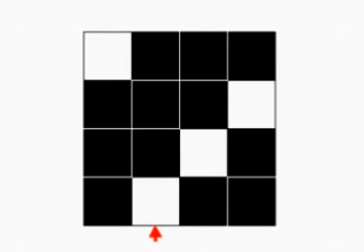The third warp yarn has a warp riser, then a warp sinker, then 2 more warp risers. The final warp yarn in the repeat has 2 warp risers, a warp sinker, and another warp riser. The pattern is repeated in both the vertical and horizontal directions and repeats on 4 ends and 4 picks. As shown, the twill may have a right-hand or left-hand angle to the twill line.